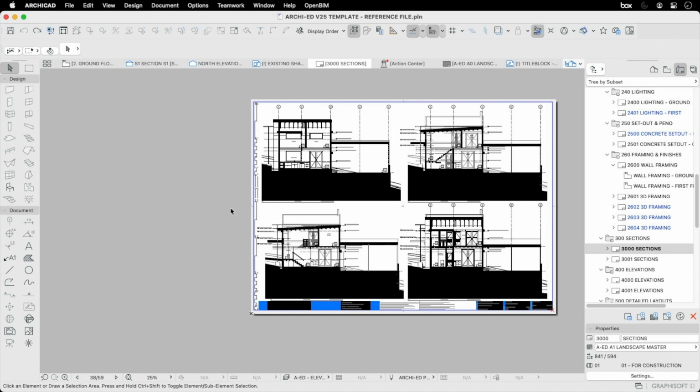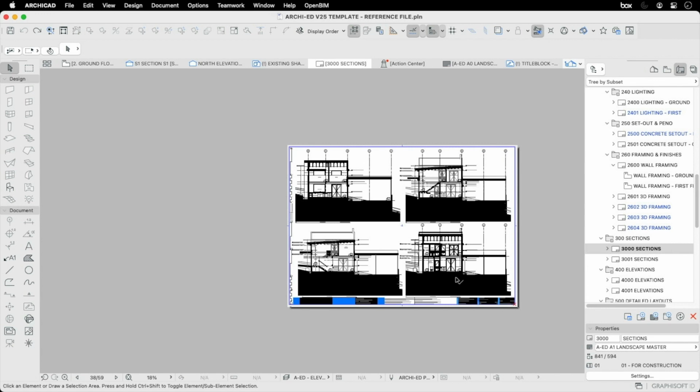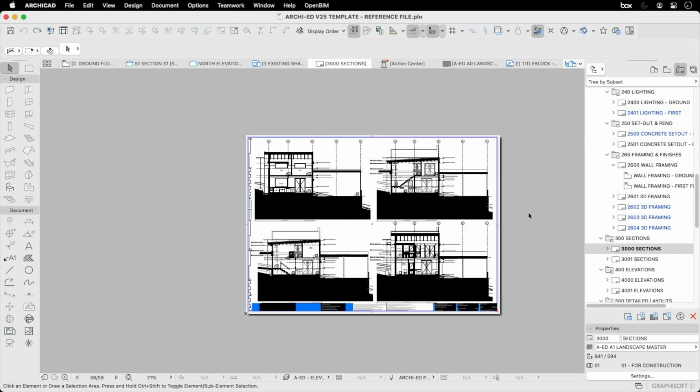If I go to pick up prints and they've just clicked print to scale, for instance, or fit to scale, and therefore they've not taken account of the percentage, then that's going to destroy the drawings. The drawings are still going to look accurate, but they're not going to be printed to scale. So it's very important, because I've put thousands of hours into doing my drawings, I need to make sure that if I want them to be printed, they get printed to scale. And that's how we confirm that, by having this graphic scale on the side of the page.